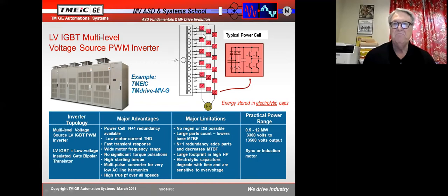I had 13 of these drives when I was at the steel plant, and when they ran really well, they were astonishingly good. I was very happy with them, but because of those electrolytic caps, we got to where we never wanted to de-energize the drive. I'm exaggerating, but it seemed like every time we turned it on, one of those big electrolytic caps would blow up. And in a medium voltage drive, you're looking at maybe $10,000 per cell to replace one of those cells. So that was a kind of a drawback.